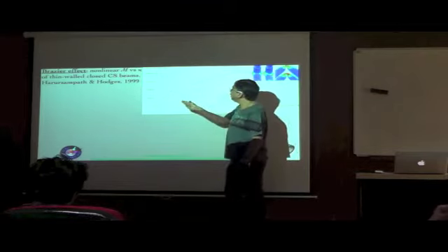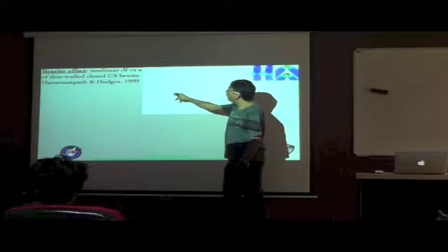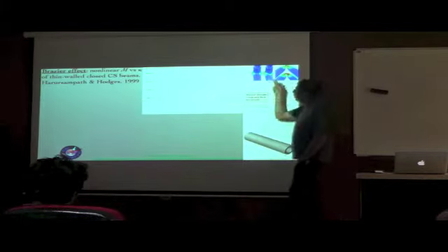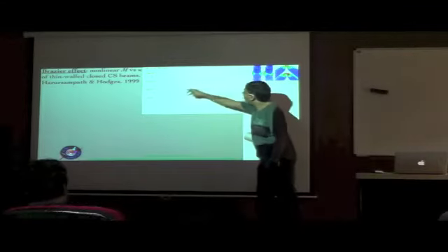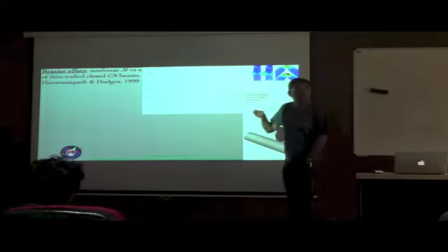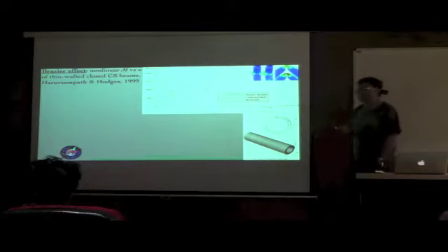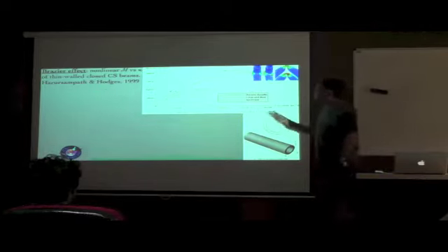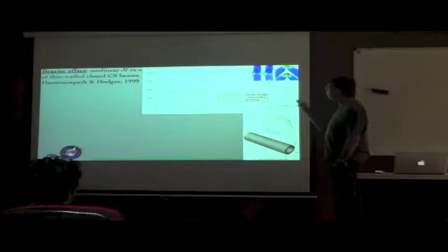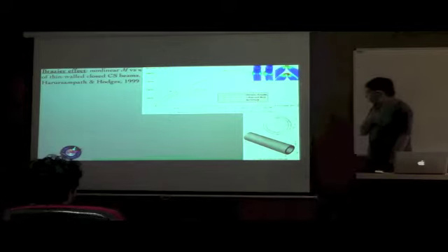But basically the idea is that we now have an asymptotically correct theory, which, though numerical results are presented for specific layups here, has closed form analytical solutions for any arbitrary layup as well. You just need to plug in the actual angles for that particular layup, and then you can make this plot of the bending moment versus the curvature.